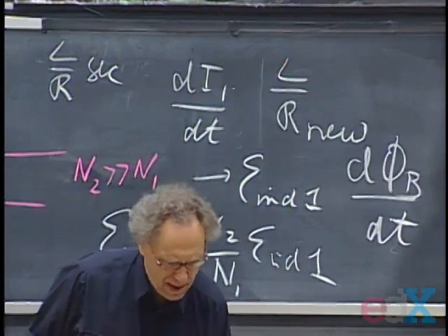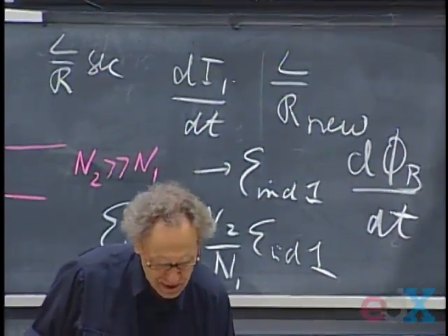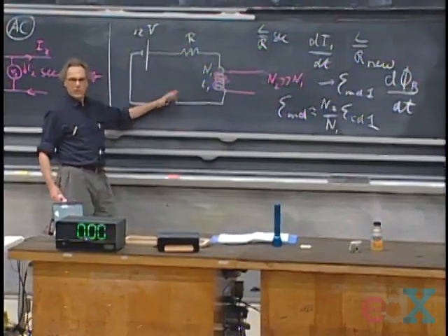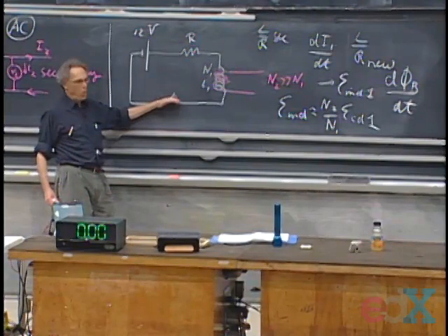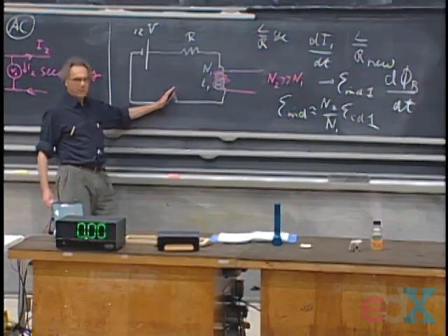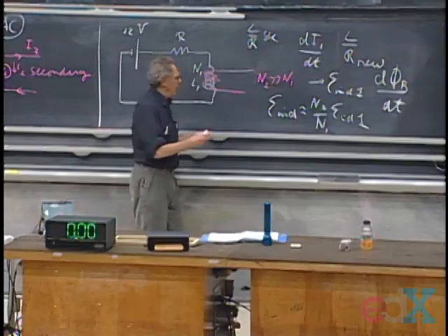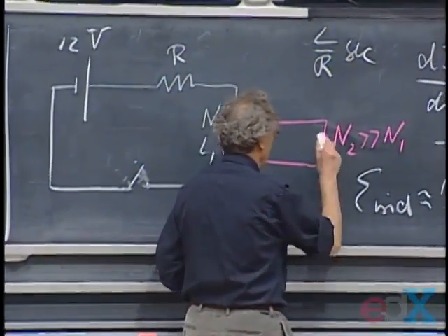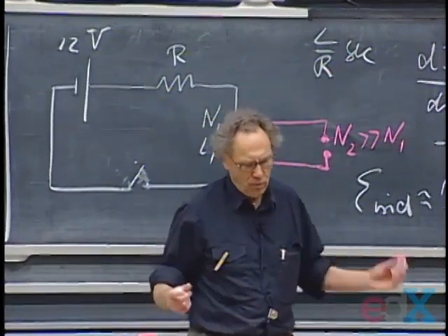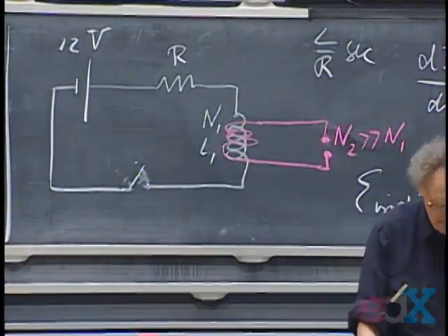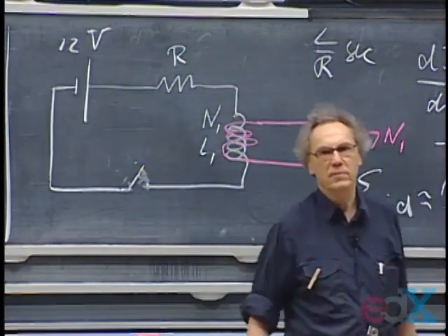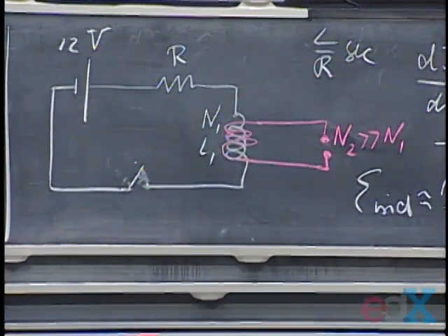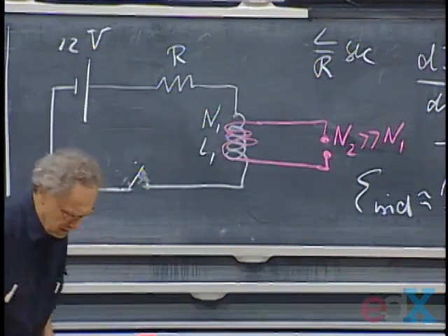And so what is happening with your car, without you realizing it, is there is a circuit that closes and opens and closes and opens and closes and opens. And it's only when you open it that you get this pathetic high voltage here and that the spark flies over. And if you run your engine at 3,000 RPM and you have a 4-cylinder, that happens 200 times per second. But it is the breaking that does it.